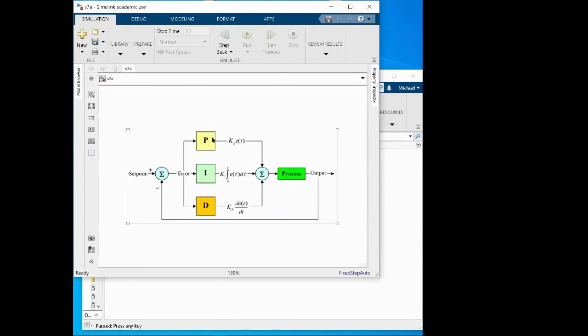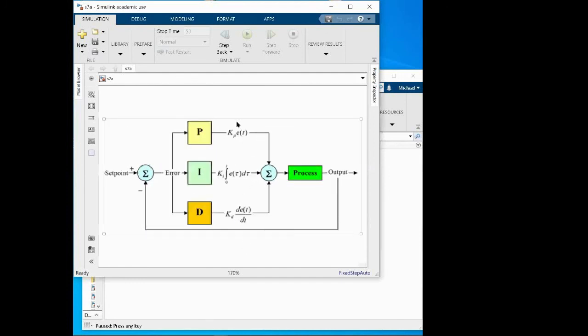Now, what can the PID controller do? It uses the proportional part, just a multiplication factor of this error. E is an error. Can you see it? Just multiplication. The integrator part of this PID controller makes an integration of this error, and it is also part of this feedback. And the third is differentiation. It makes the first derivative of this error, and is the third, the last part of this controller.